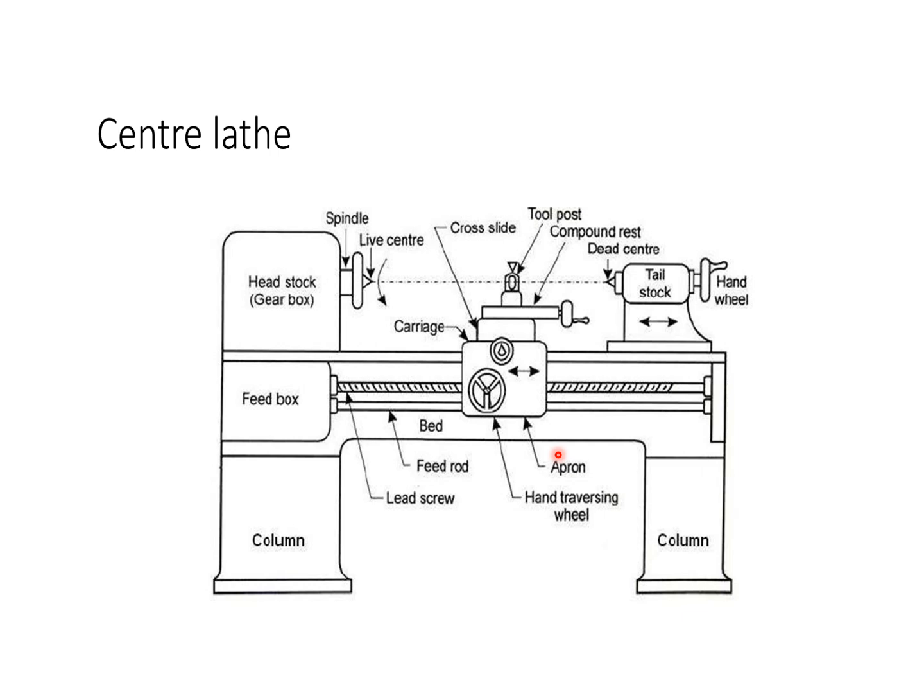First, saddle. So, saddle, it carries the cross slide. It carries the cross slide, compound rest. See, this is the compound rest and tool post. It is an H-shaped casting fitted over the bed. It moves along two guideways. Cross slide, it carries the compound rest and a tool post. It is mounted on the top of the saddle. It can be moved by hand or may be given power feed through apron mechanism.